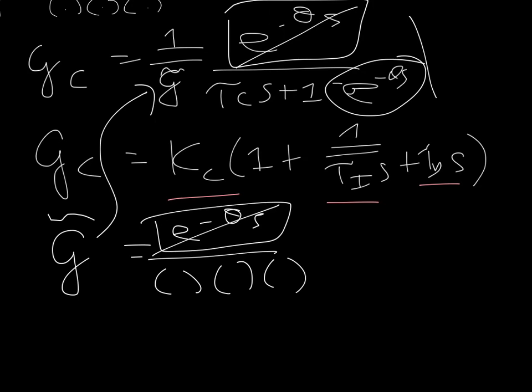And if we're trying to approximate these two by one another, in other words, if we're trying to approximate this big difficult controller with a simple off-the-shelf PID controller, we'll have to get rid of this dead time. Depending on the order of the controller, we'll typically multiply it out and then do some kind of simplification or approximation of e, and we'll only really bother with this e, the one in the numerator.